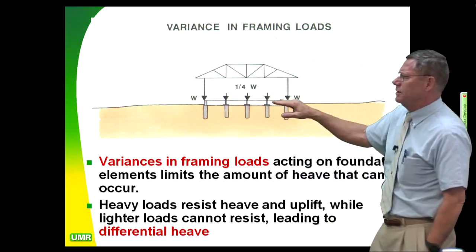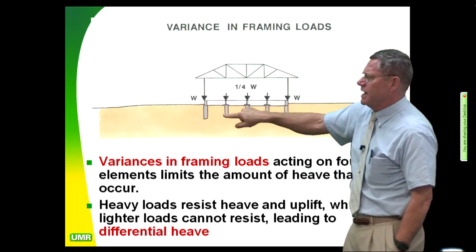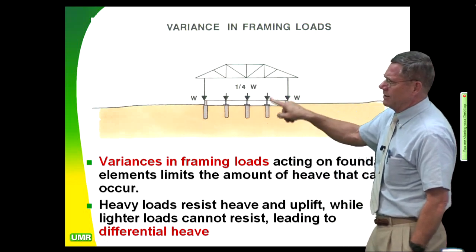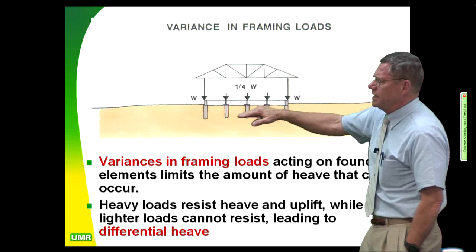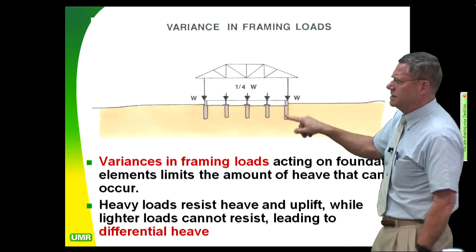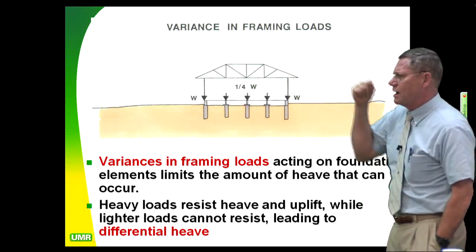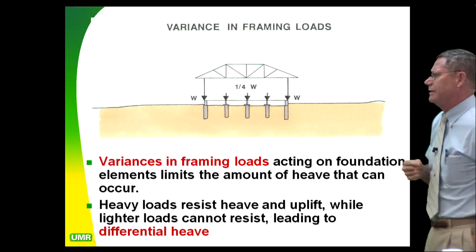But that can also lead to differential heave, because these guys aren't going to get as much load, so they're going to tend to heave more than the ones next to them over here. Now we're going to talk about this over and over and over until I think you get it.